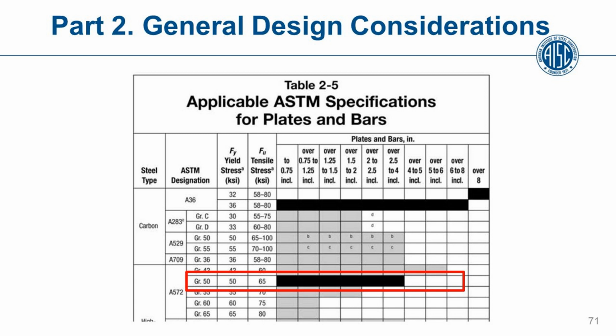Okay, great. And somewhat related, we have some new materials and then some new shapes. Can we expect the new rolled shapes coming out of most of the mills to follow these new values? Well, that's part of the problem. They're listed. They are produced by some mills, not all of the mills at this point in time. And that's why I emphasize you should always check AISC's website to see what mills produce them, because we have that listed on our website.